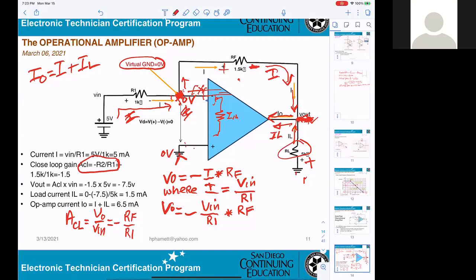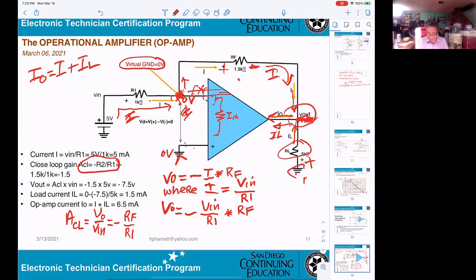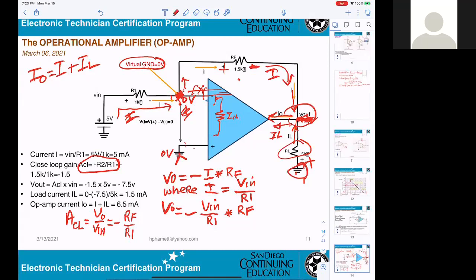Right. That means if I ask you to measure, connect the DMM high side to here, low side to ground. Okay. The only reason I was asking is because the ground is positive and the output side is negative. That's why you get negative voltage.